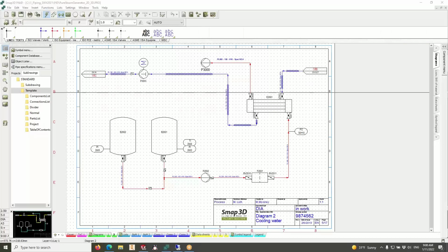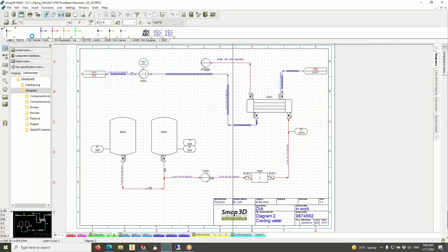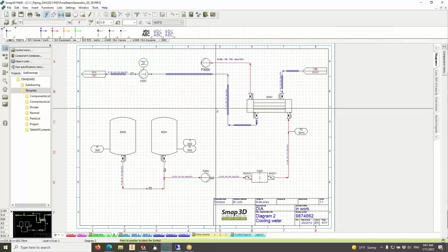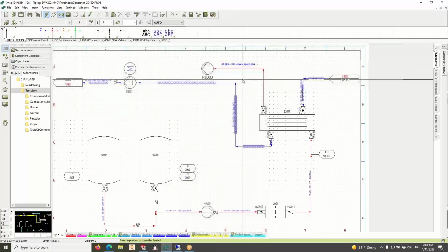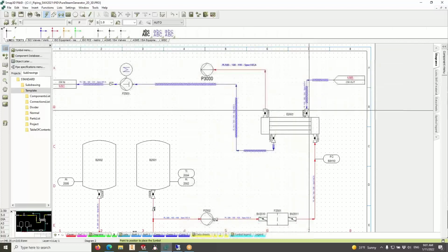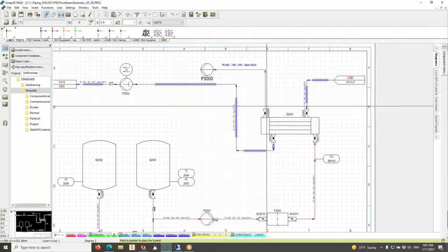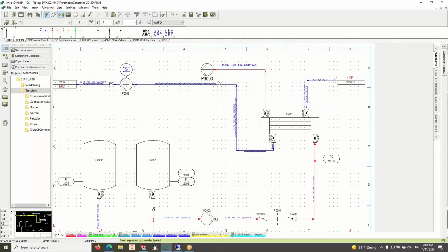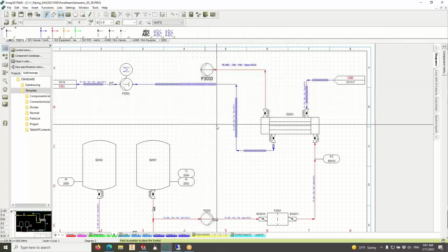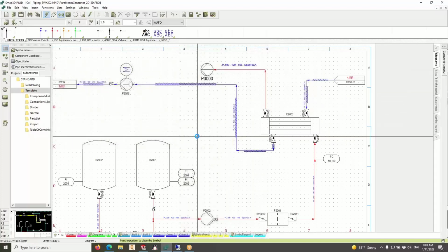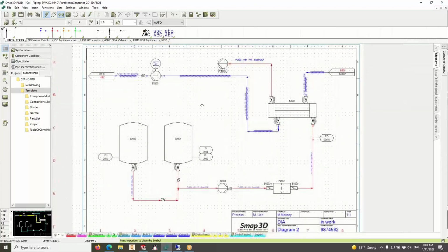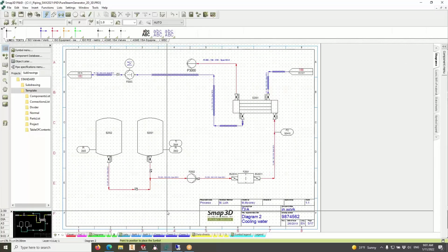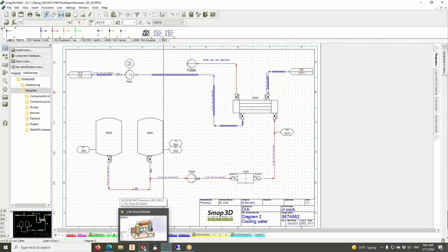Okay, good. All right, then let's see, how do we get this information over into 3D, into SolidWorks, to do that side of things? Because right now, we don't know how long this piece of pipe is. We don't know if there's only one elbow or if it takes 25 elbows to work around the other things, and how many flanges and fittings are going to be necessary. So again, with just a schematic, we can get the equipment, but we don't have length information and how much pipe we need. For that, we need to do it in 3D.